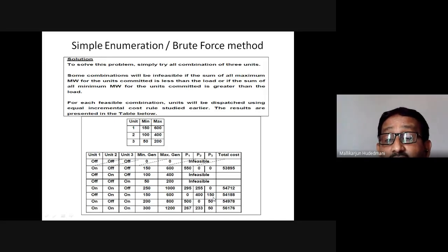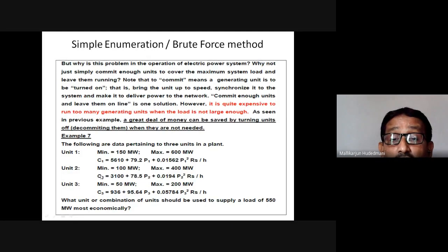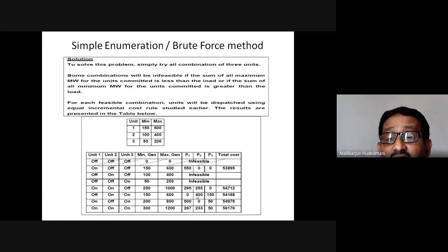So therefore, you might ask me, why not the other way? Why not a higher capacity on machine 3, a lower production on machine number 2? It all depends again on the fuel cost function. The cost of fuel put on machine 2, machine 3 matters. The coefficients over here determine which machine is relatively cheaper in production of certain megawatt for your combination. And here, I am quite sure machine 2 finds its best scope for higher production than machine number 3. So that is put with 400 megawatt and 150 megawatt. Together 550 is served for us.